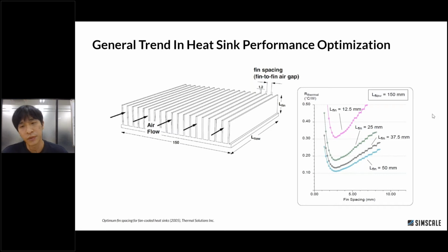1.175, about 0.085. This number is smaller than the combined thermal resistance of, for example, the heatsinks of 37.5 millimeter height and 12.5 millimeter height, which is about 0.92, or one single heatsink of 50 millimeter height, which is about 0.11.